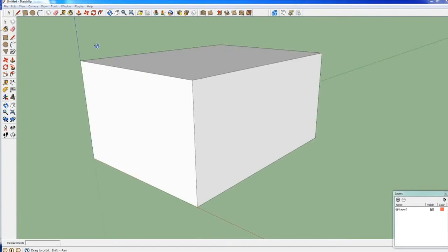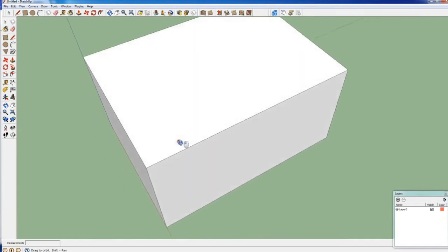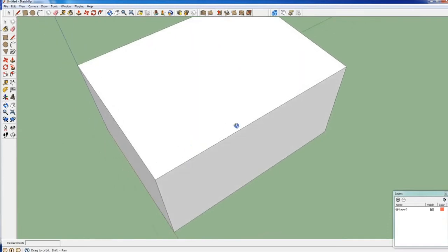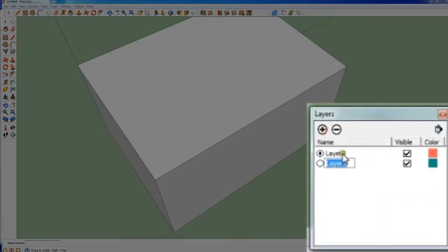Roughly now I can see that this is the basic shape of the auditorium, and this gray rectangle will be my ceiling, the ceiling of the auditorium. And since afterwards I need to have access to the interior, it's nice timing to set the ceiling as a separate layer so that I can remove it occasionally. In order to do that, I go to the layers window and I add a second layer. So far everything we have designed belongs to layer 0, but now I add the layer and I give the name ceiling.